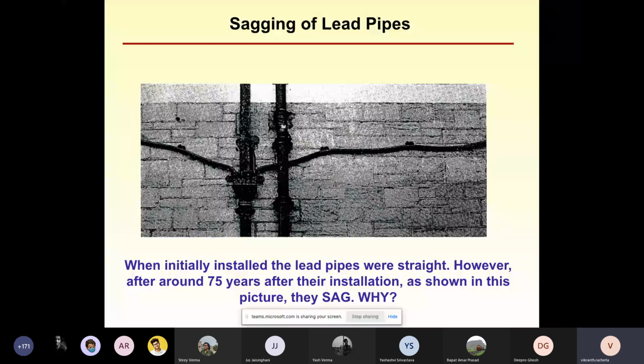So for plastic parts, the shape change is a real concern even at room temperature. So creep is something that you have to keep at the back of your head. You need to find out what your operating temperature is vis-a-vis its melting point in Kelvin, and based on that you have to decide whether you want to be concerned about long-term effects or not.